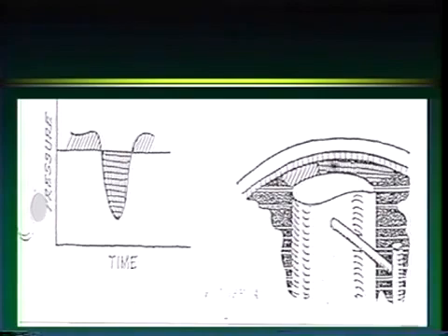Now, this trailing edge of the foil has this wing shape, okay? And what's happening here is that it's actually creating a low pressure zone. If you use Bernoulli's equation, you can see that the velocity here is going to be higher, and you can calculate that the pressure here is going to be lower.